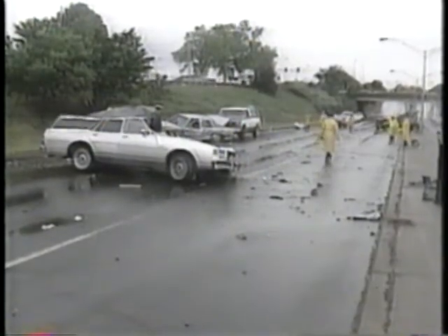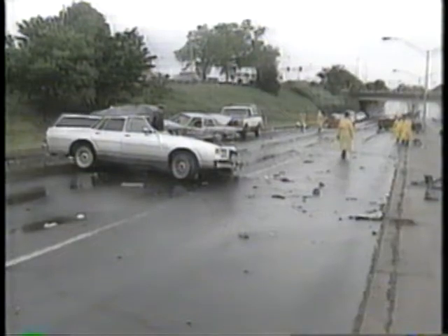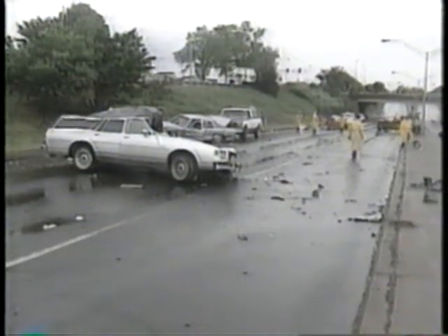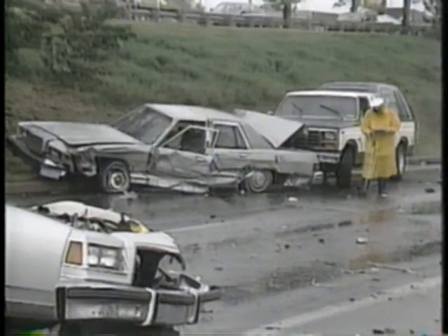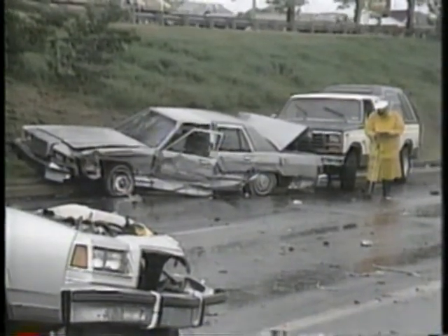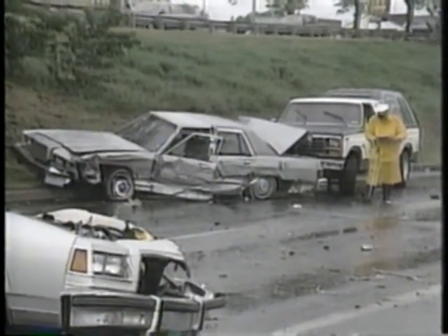In absorbing the crash forces of an accident, vehicles may be severely damaged. Often, the forces of impact travel through the body panels and up the body pillars, buckling the roof and other panels. This is intentional and allows the deceleration forces to be spread out on the outside of the vehicle, while protecting those inside the passenger compartment.